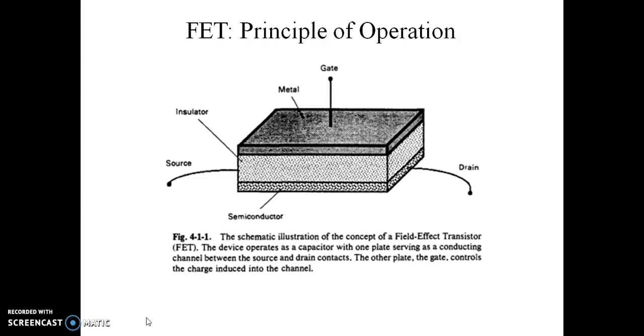I have already said that different kinds of field effect transistors are available, such as MOSFET, MESFET, JFET, etc. These devices differ in the gate material and in the location of the gate with respect to the channel, how the gate is isolated from the channel, and what type of carriers are induced by the gate voltage into the channel. For example, electrons are induced in n-channel devices, holes are induced in p-channel devices, and both electrons and holes in double injection field effect transistors.